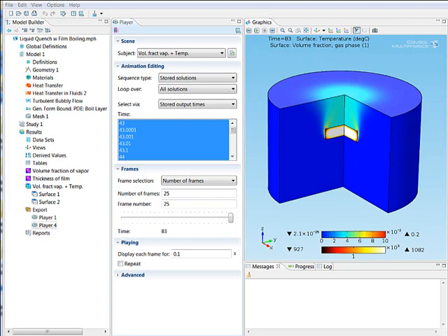This demonstration looks at a model of the initial phase of a liquid quenching process called film boiling, which happens when a vapor layer separates a hot solid from a cool liquid. Quenching into liquid media is an extremely complex process involving a variety of physics operating on vastly different scales. The near-wall boiling processes that strongly influence heat transfer from the part to the quenching medium operate on a scale that is many orders of magnitude smaller than the component size.